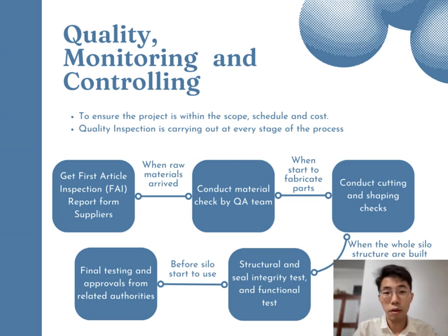After the silo is built, a structural inspection is carried out to inspect the structural integrity of the silos, including the walls, foundations, and roof, to ensure that there are no cracks, leaks, or other signs of damage. Seals and joints of the silos are tested to ensure they are properly installed and watertight to prevent water leaks from the water cooling layer to the grain storage layer.